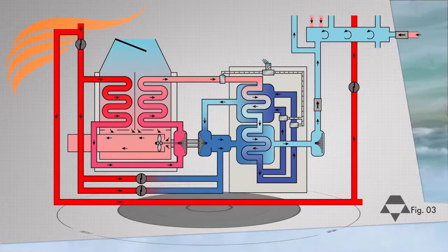Packs discharge air at a value that is sufficient to maintain the flight deck, passenger cabin, and cargo areas to their automatically or manually commanded temperatures. 2 redundant channels in 2 separate controllers control each of both packs. If one channel in a controller fails, a system logic commands the other channel to assume command immediately. And so we have bleed air. But what exactly happens to it when it goes through either pack?